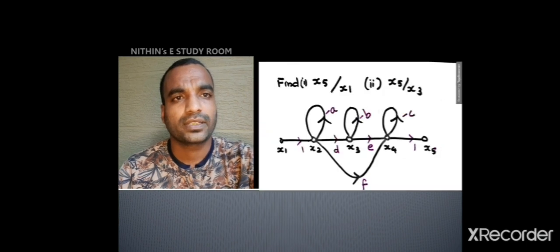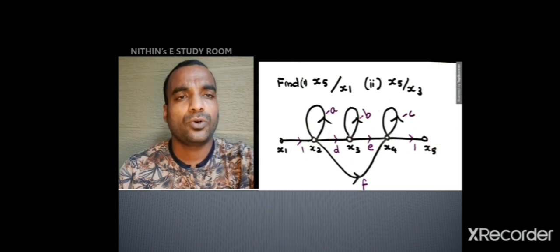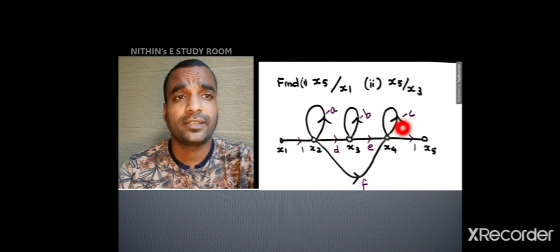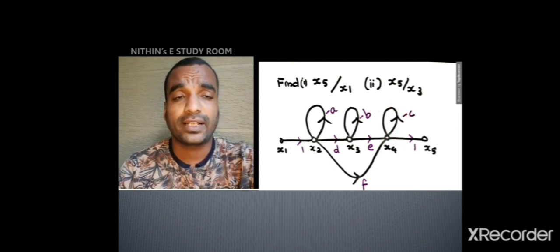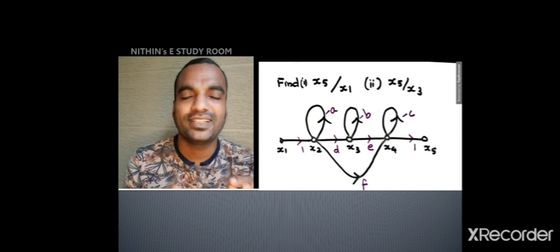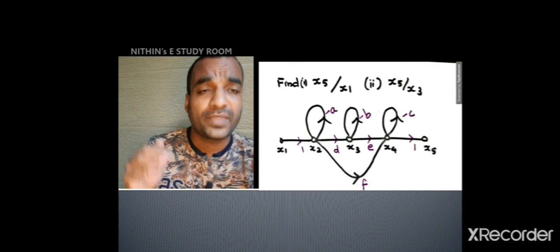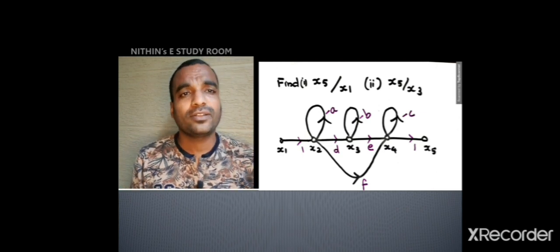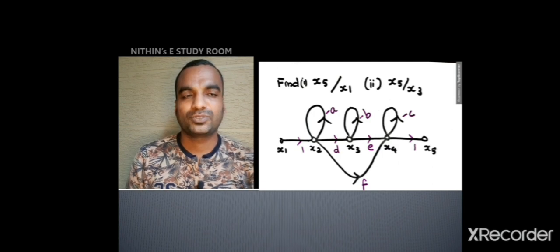Okay, no drawings are given. So this is the first forward path, and all the loops are placed on that forward path. All the loops are touching on that forward path. So it is very clear that in the equation of delta 1, you have to put L1 equal to 0, L2 equal to 0, L3 equal to 0, because all these three loops are touching on your first forward path. So that is the case.